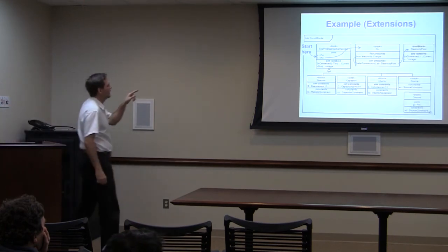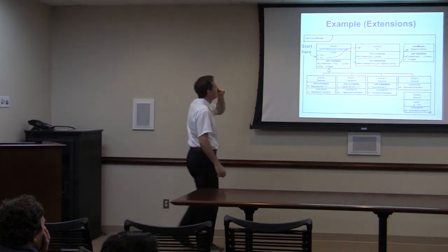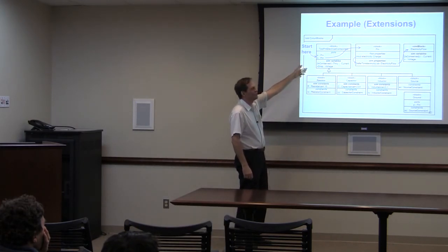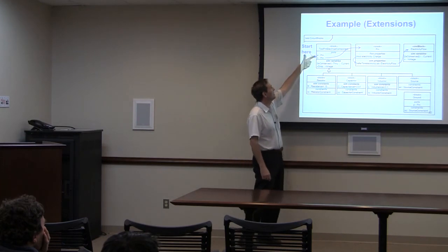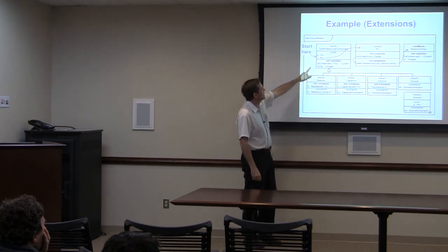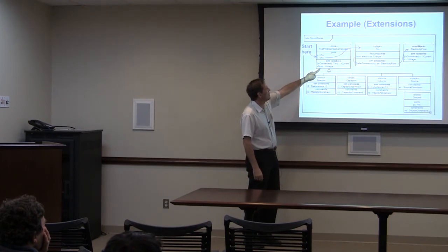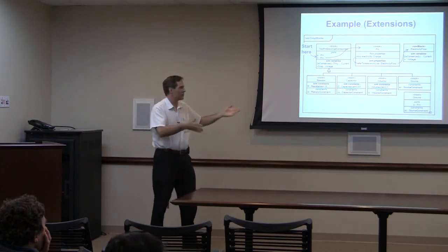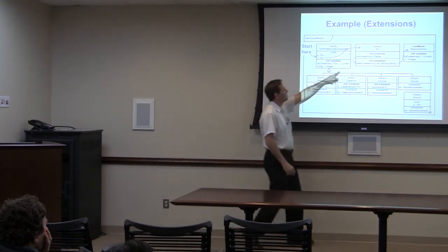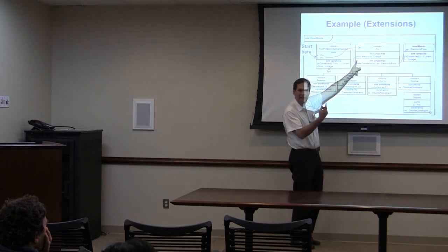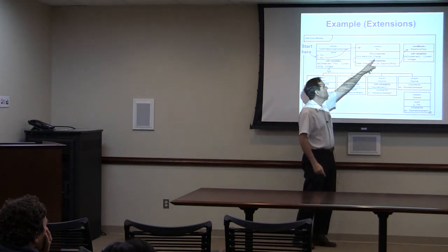Then if you look at the extension, you say, OK, this is an abstract block that captures the 2 pin components that we saw. You have the P role and the N role and their types. They're the ports. These are the sim variables that go on these components. You want to know what the current is going through the component and the voltage drop across it. And similarly with the pin, this is in-out, meaning it's bidirectional. You have electricity flowing in and out.